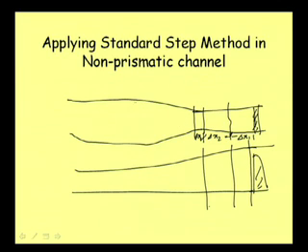These parts are expanding quickly, and although we use a factor k for computing eddy loss, it is still better to make a smaller section when it is significantly expanding, so that the assumptions we had for the prismatic channel can be valid for this part. So we consider a smaller part and then calculate.